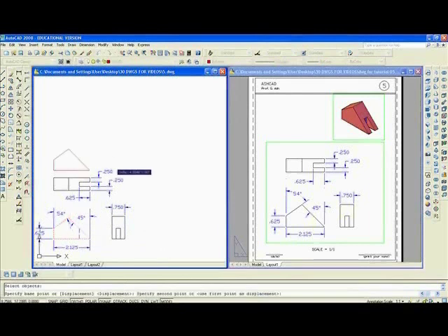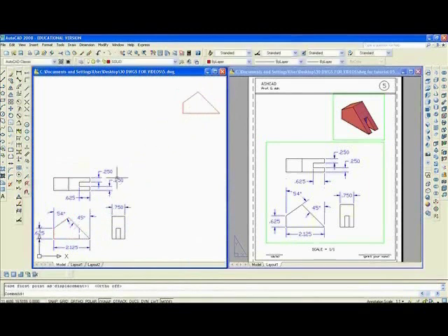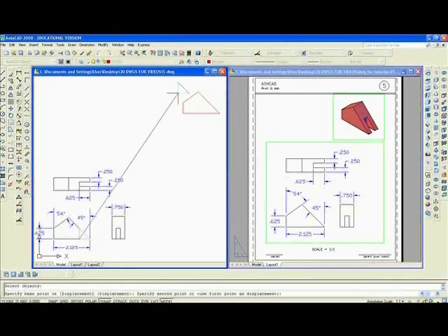And move that with ortho off, up and to the right. You also want to trace over the little right triangle, so you take polygon, M, enter, L, enter, and move the right triangle up as well.